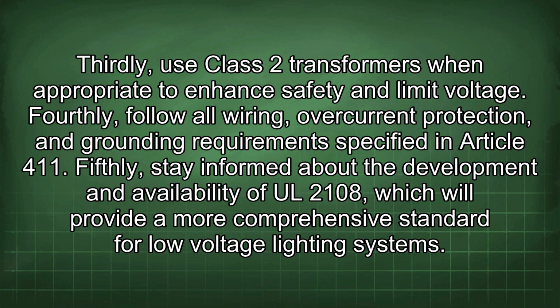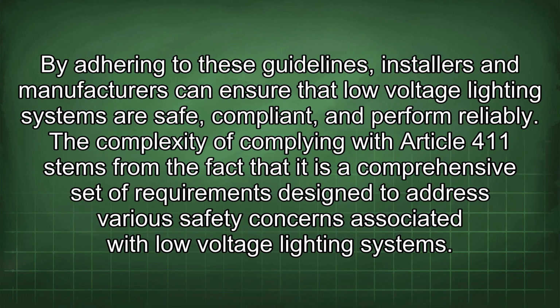Fourthly, follow all wiring, overcurrent protection, and grounding requirements specified in Article 411. Fifthly, stay informed about the development and availability of UL 2108, which will provide a more comprehensive standard for low-voltage lighting systems. By adhering to these guidelines, installers and manufacturers can ensure that low-voltage lighting systems are safe, compliant, and